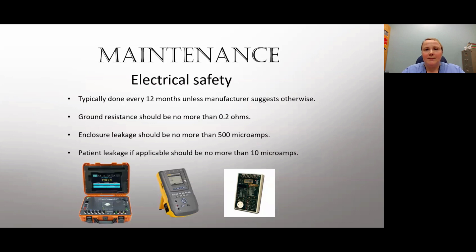Now we're going to get into the maintenance of some of our lasers. This is mostly biomedical related, so electrical safety. Most electrical safety is done every 12 months on our lasers, unless the manufacturer suggests otherwise. Some of them are 6 months, 3 months. We have different types of equipment. It depends on the manufacturer recommendation when electrical safety and checkouts are to be done.